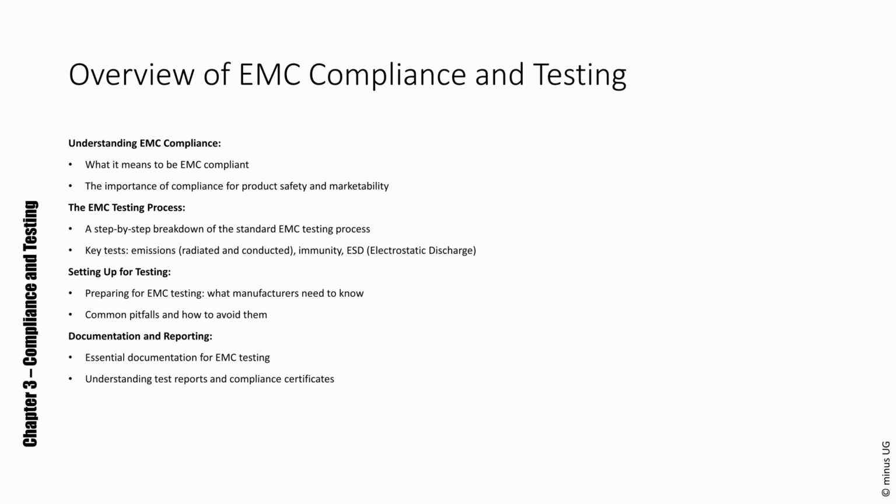Understanding the applicable EMC standards for the product. Ensuring the product is in its final design form, as changes post-testing can affect compliance. Choosing a reputable and accredited testing facility. Common pitfalls to avoid include inadequate preparation, misunderstanding the scope of required testing, and not accounting for potential design changes after testing. Documentation and reporting.